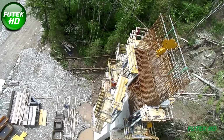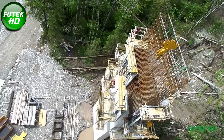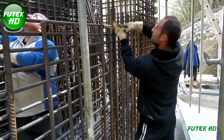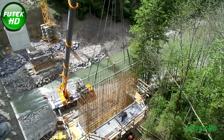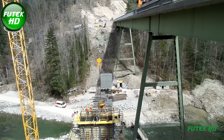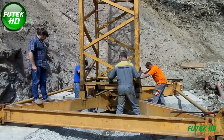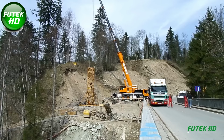The cross-section of the bridge consisted of slabs with variable heights, 2 meters at the middle of the span and 3.5 meters at the base, giving the structure a total width of 10.5 meters. This design ensured a more stable and durable bridge that could handle increased traffic and provide greater safety.